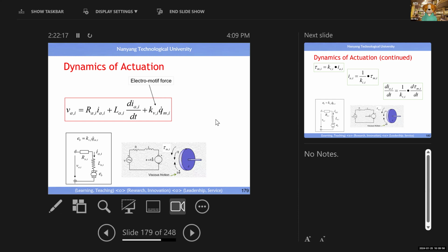Conservation of energy. But if you go into more detail from the electronic side, you have total voltage equal to the voltage drop across the resistor, the voltage drop across the coil, right? And plus the voltage generated by a rotating loop inside the magnetic field. Because when it's rotated, it behaves like an electricity generator. It will produce voltage, right? So these three together must equal the input voltage, right? So you see this is a parameter which represents mechanical energy already, right?